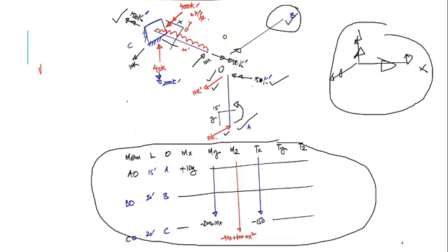So this 10 kip would be taken by joint O of member CO. Then 10 kip would be balanced here as 10 kip. Next, the load on this member CO is a UDL, 2 into 20. 2 into 20 gives 40 kips, so I have to apply an equal and opposite 40 kip upwards. Okay, next.